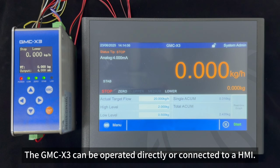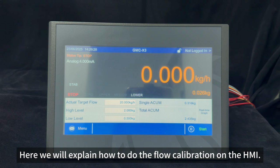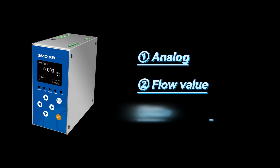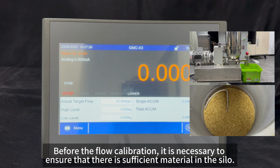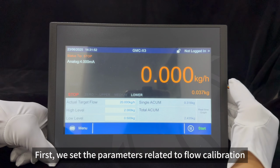The GMC-X3 can be operated directly or connected to a HMI. Here we will explain how to do the flow calibration on the HMI. The flow calibration of the GMC-X3 includes manual calibration and automatic calibration, involving the parameter settings such as analog, flow value, and calibration switch. Before the flow calibration, it is necessary to ensure that there is sufficient material in the silo. First, we set the parameters related to flow calibration.